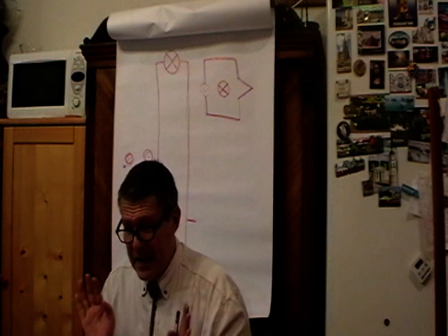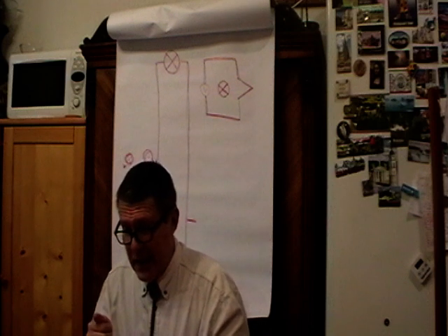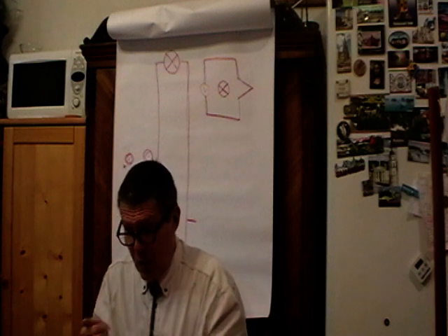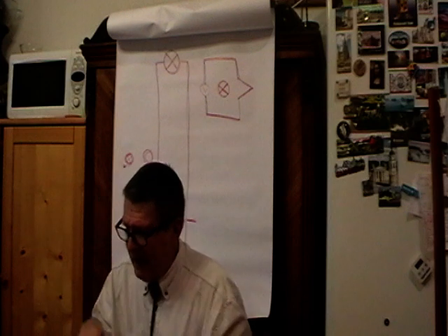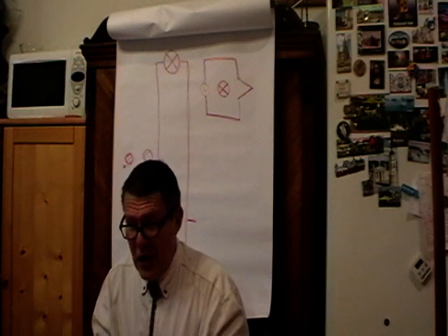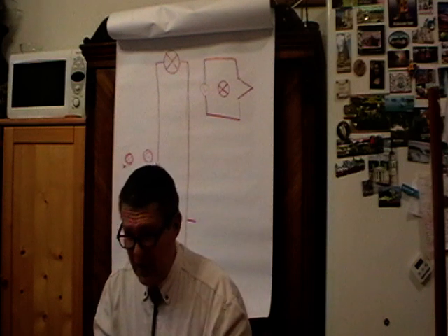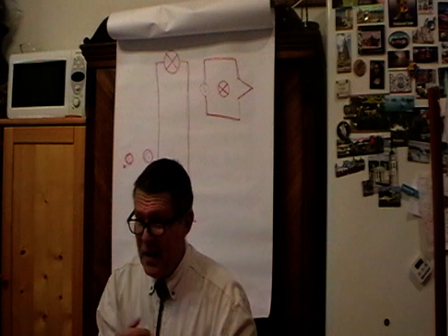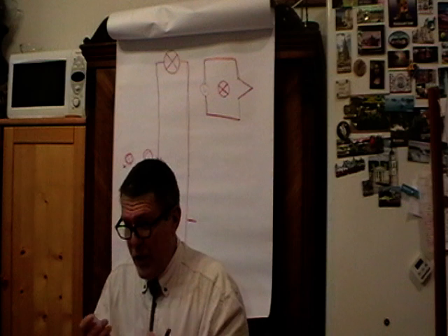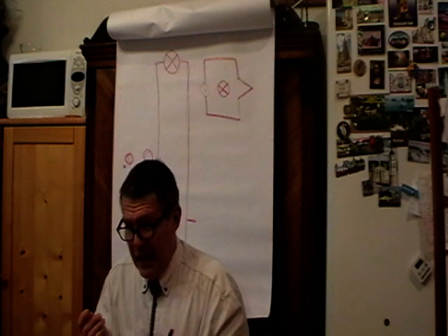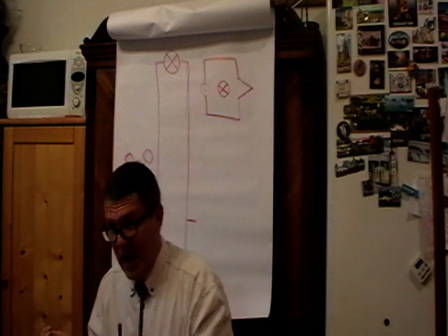And so there is some value which is specific for one transmission line, for one cross-section of the line, depending on the shape and dielectrics and whatsoever, which has a special value which is called characteristic impedance. We will get to that later, but the important point is there is a characteristic impedance which is given as a ratio between a voltage and current.